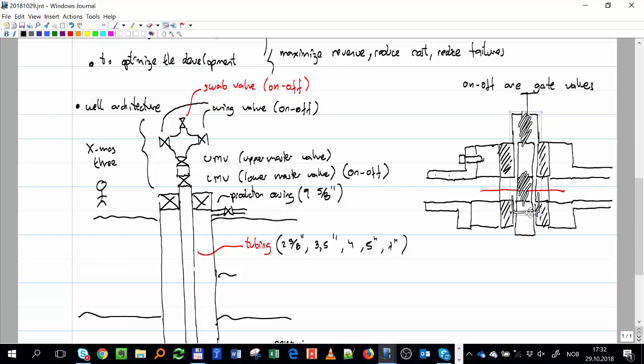But if you pull it up, then it's blocking. The very important thing is that these two surfaces make contact. That's where you have the seal. If you have a side with high pressure, the pressure tends to push all of that slab, all of that gate, and makes contact between these two. So you will have the seal on this contact area and on that contact area, or the opposite, if you have the flow on the other side.